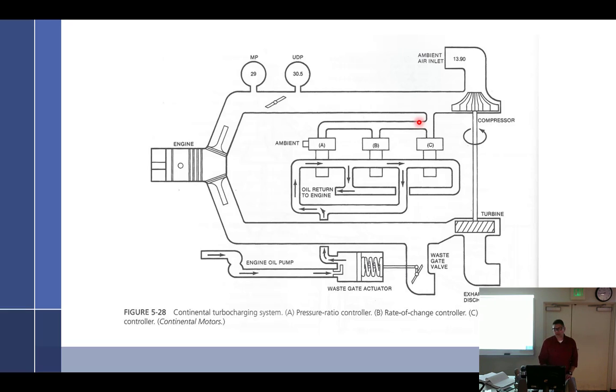And so I would go to, we have a thing in our aircraft that's called a VSI, vertical speed indicator. Inside of there you have a bellows with a very tiny leak. Whenever you change altitude, it wants to equalize, but it takes a while to equalize. The fact that you've changed altitude makes the bellows expand or contract, which is attached to a needle. It expands, but then you stop going up and it equalizes. Okay, so I think I could probably make something like that with this, just using a bellows and a calibrated leak.